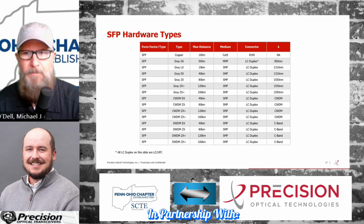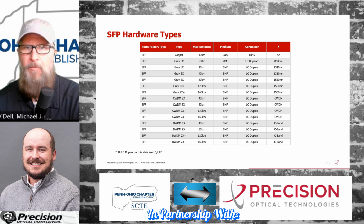The reason is you'll see a data sheet for a wideband or gray optic, and let's use the gray SX, for example. That's a short reach, 850 nanometer. But if you take a closer look at the data sheet, it's a wideband because 850 is the center, the average wavelength being transmitted. It can actually vary anywhere from 830 to 870. So hence why we call it wideband.